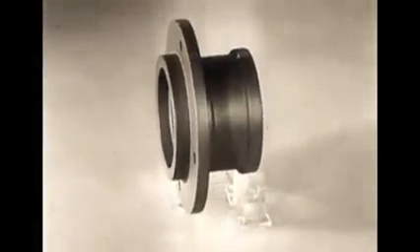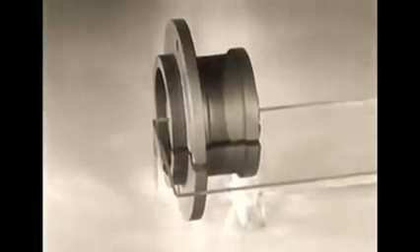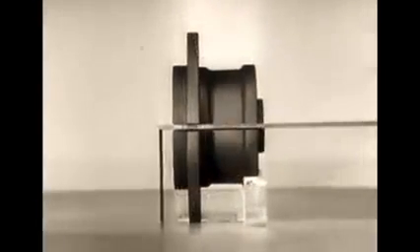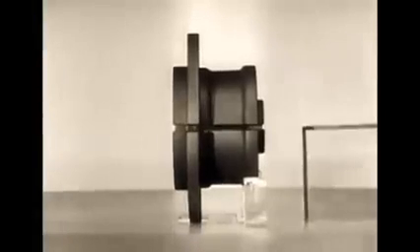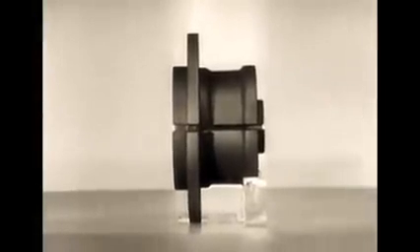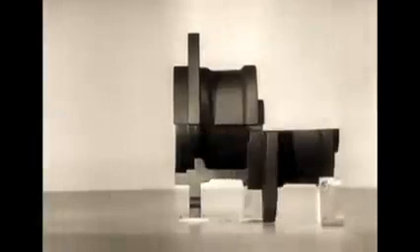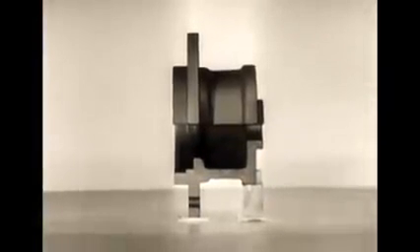In such a case, you can imagine that the cutting plane goes only halfway through the object to the center, and think of only 1/4 of the object as being cut away. This method creates a half section, showing both outside and inside details.